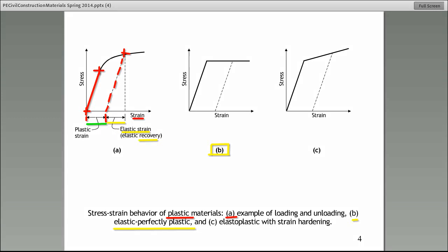All right. First, elastic. We refer to the elastic part as this. It's linear up to a point. That point I call the knee point. All right? And then what happens at the knee, the stress-strain curve has a horizontal relationship, just like that. And that is why it's called perfectly plastic. It's plastic because it's beyond the elastic limit, but it's perfectly plastic because it's horizontal.